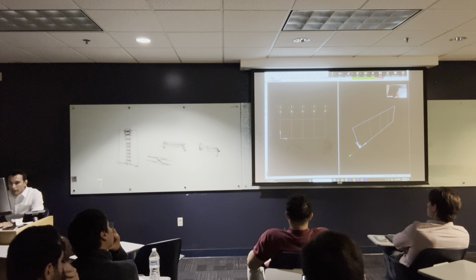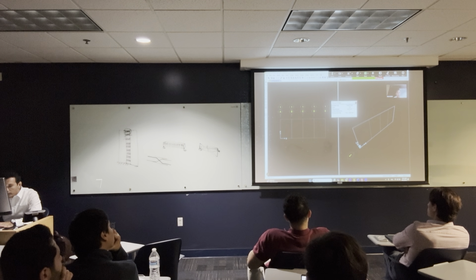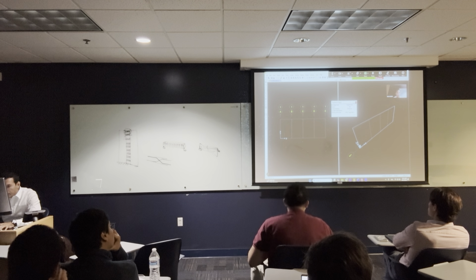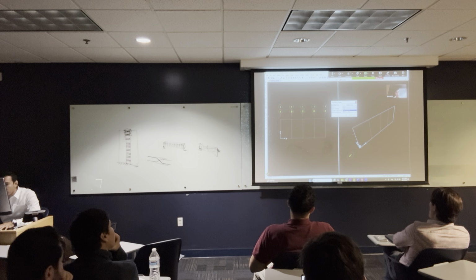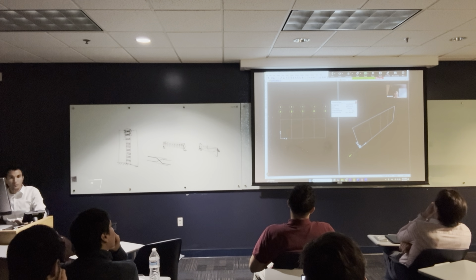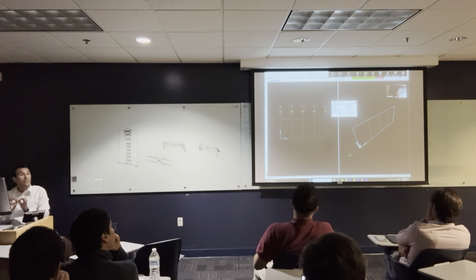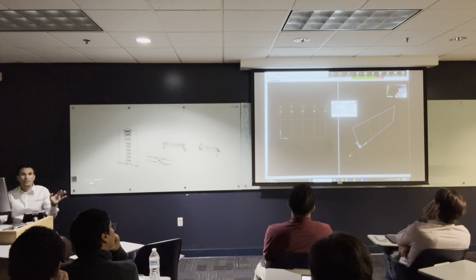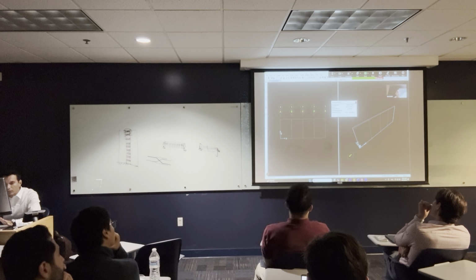I'm going to click on this frame. Once I click on this frame, it's going to open a box called the properties of the object. And it asks me, what is the section type that I want to use? So I have an I-beam 500 and a beam 25 by 7. I can use either. So let's say I'm going to make a concrete truss. If you didn't define these cross sections, SAP 2000 is going to develop its own cross section. Okay, so right now I'm ready to draw.